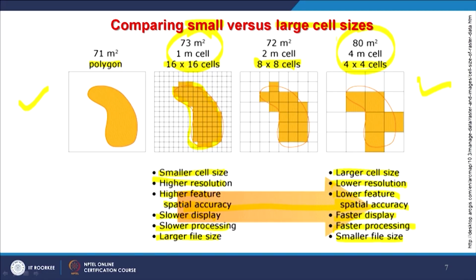So, it depends on our requirements, the targets for projects, and the scale at which we have to produce the result in GIS. If we can decide that, then we can decide which resolution data to employ, because now choices are increasing even for DEMs of different spatial resolution. At 30 meter there are 3 choices, but below 30 meter there are few choices. At 1 kilometer again you have few choices, and at 90 meter not many choices.